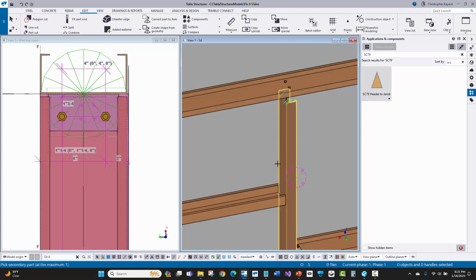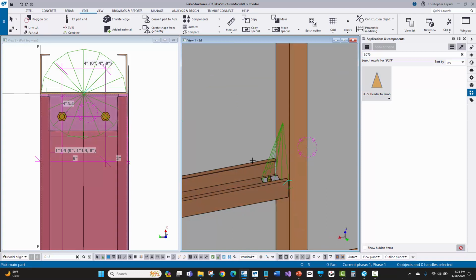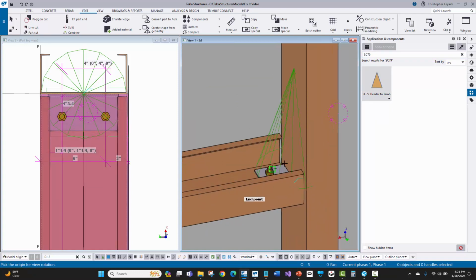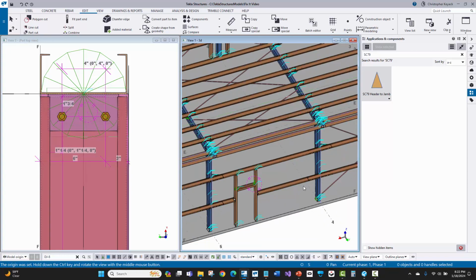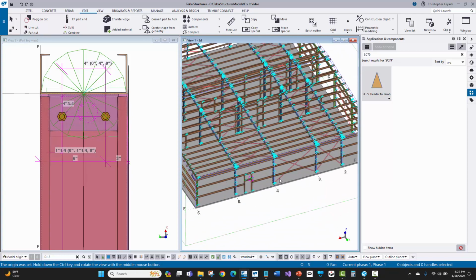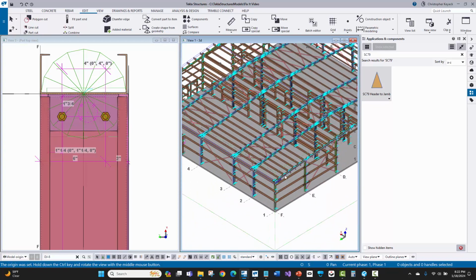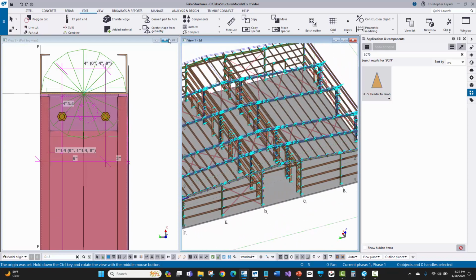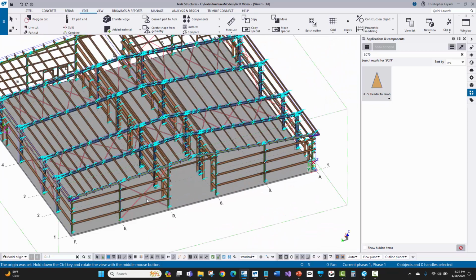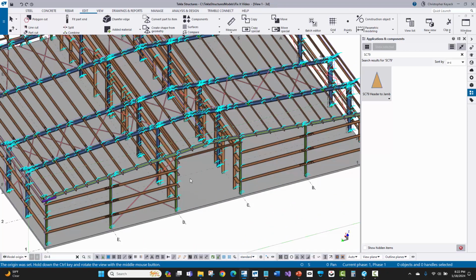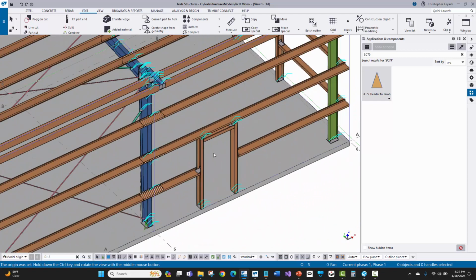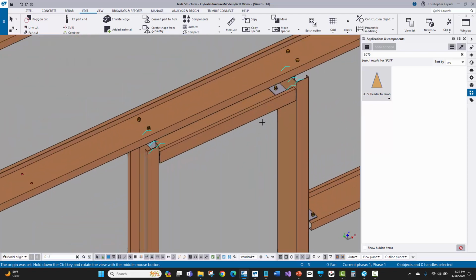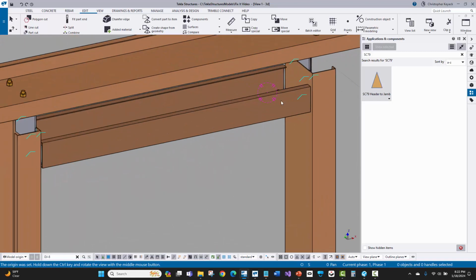So now I should be able to just click the jamb, click the header, and boom, the bolts are there and it is offset correctly. Now, I can basically just go to all the other openings in the model and find those, and it's a lot easier instead of creating all these additional views like I did here and then moving the plate manually. I can just go find those openings wherever that header is at, and then wipe out what's there and replace that with my custom component.